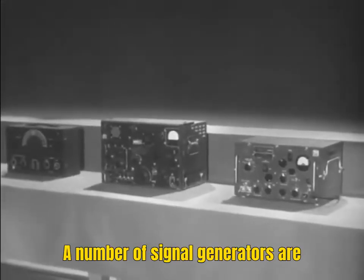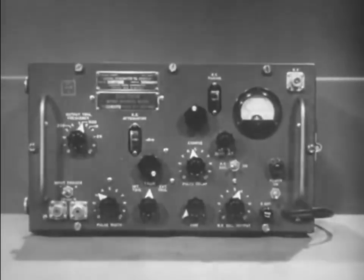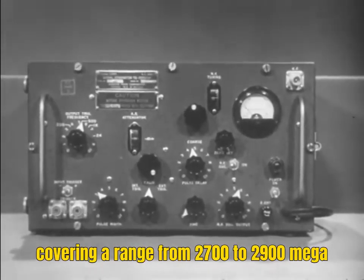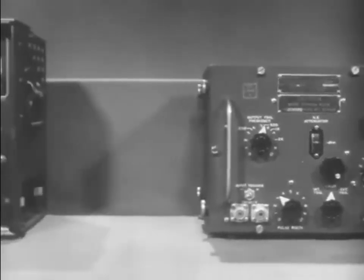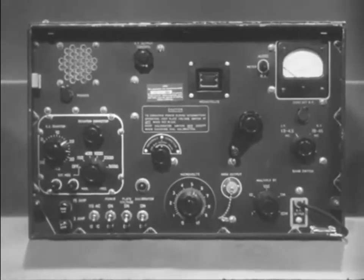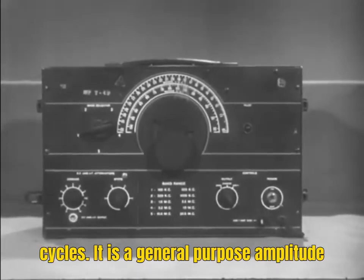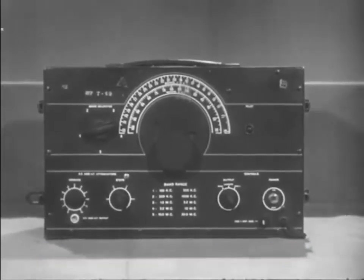A number of signal generators are required for the different ranges used by the various types of signal equipment. This signal generator is designed to operate on the ultra-high frequencies, covering a range from 2700 to 2900 megacycles, and is used in radar work. This one is designed to align, test, and calibrate frequency modulation radio receivers. This unit goes from 100 to 32,000 kilocycles. It is a general-purpose, amplitude-modulated oscillator covering a wide range of frequencies used in radio work.